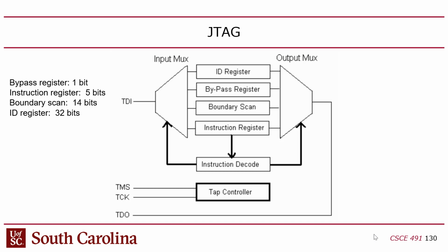registers that are defined. There's the ID, and this is pretty kind of cool, the JTAG defines a specific instruction as the ID register. So if I want to know what's on the JTAG bus, all I have to do is put it into the instruction register read state, right?